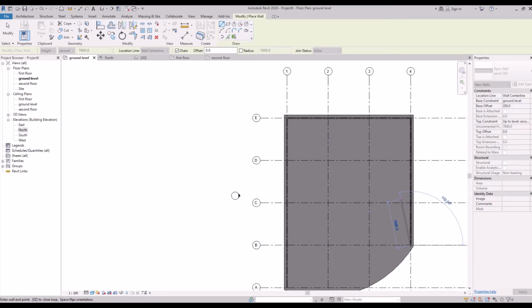When you're drawing walls, it is similar to drawing the floor. You have all these draw types that you can use. So if you want to draw a rectangle, let's say I will add a room here in the middle, for example. So I'll just take a rectangle, and then for this wall, I'll change it. I want it to stop at the first floor. I don't want it to go all the way to the second floor. Okay, so I can just draw this here.